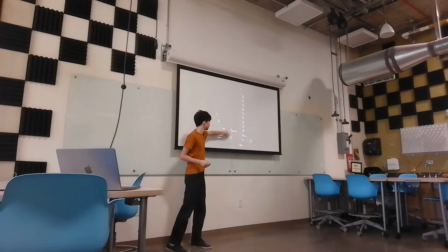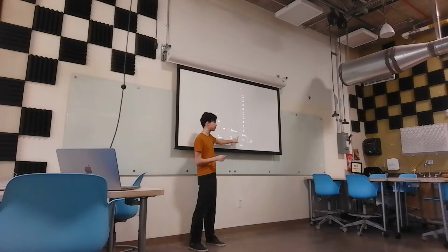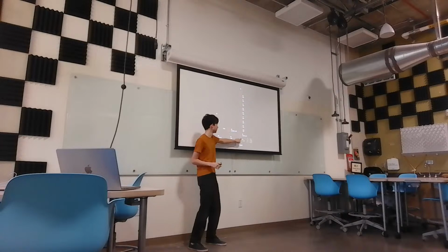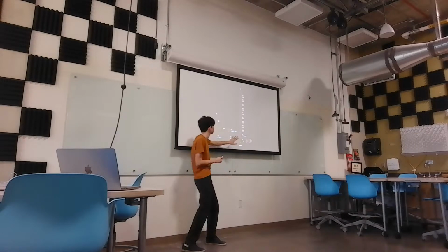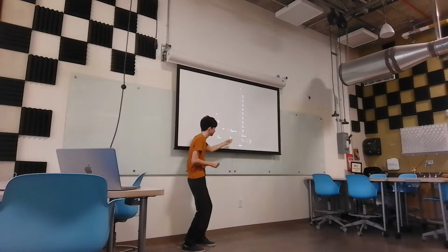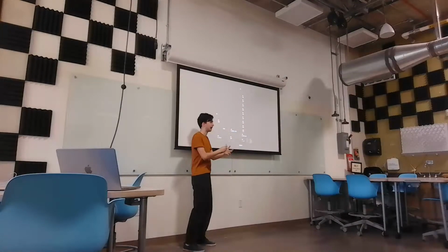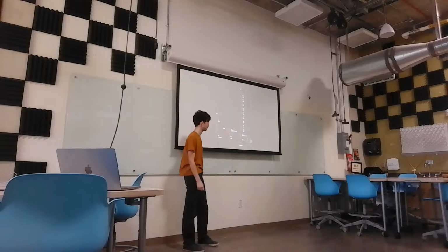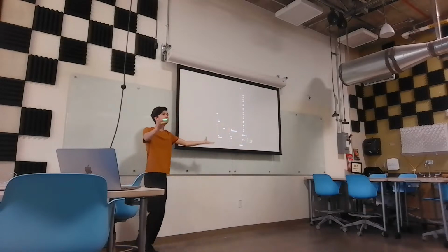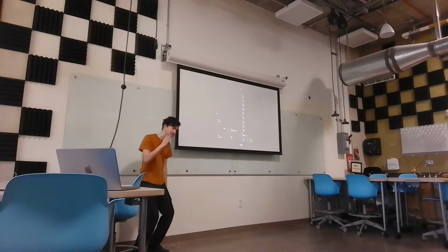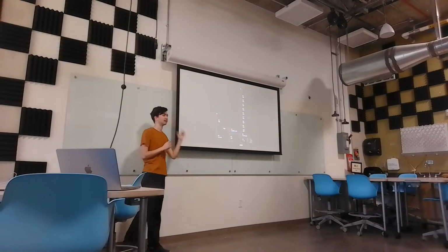Ignore this for now, because this is a wire thing. If I assert that 1 volt is here, and also another property of a BJT is that the voltage from here to here is 0.7, that means the voltage across this is 0.3. I've now asserted that the voltage across this resistor, no matter what this voltage is, will be 0.3. I can now set the current. I say, okay, 0.3 volts, these resistances will result in these currents. The universe solves it for me. I told the transistor this is the current I want, and it does it.